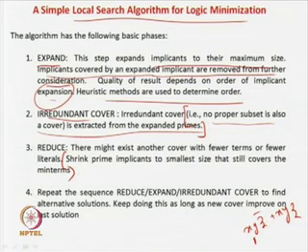So here we are not at all bothered with any types of primes. What we do is, in the expand step, expand the implicants to the maximum size. Then irredundant cover: if you have some terms which are redundant, we can eliminate them. And reduce means there may exist another cover with fewer terms or literals, so that means now you are again going to shrink it.